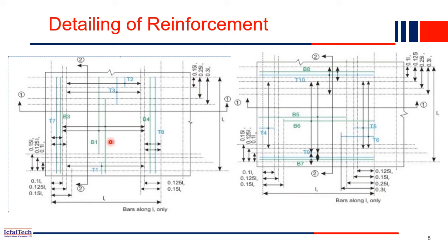Okay, why? Because this is bottom reinforcement, right? So bottom reinforcement is provided only for the positive bending moment. So positive bending moment is not there near to the support. Then why continue this bar again towards the support? No need, right?